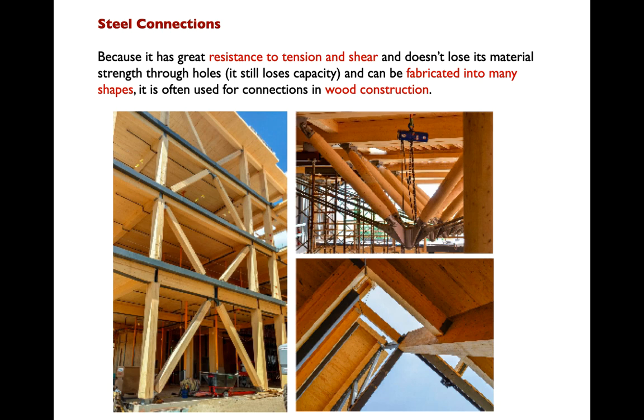In the upper right, you can see basically a three-dimensional timber truss holding up a roof, and all of those chords resolving on steel nodes that are built out of a combination of steel castings and steel plates. Again, resolving, in this case, the axial loads that are coming through that timber, using steel to create precise connections that allow for some rotation, allow for some ductility in the structure, connections that we couldn't make only in wood.